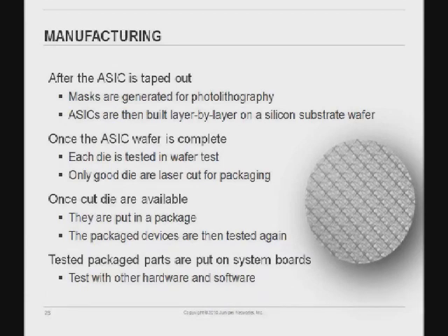And then that takes a couple of months, I believe. Once the ASIC wafers are complete, on the right side there's a wafer with a lot of chips on it, and each die is tested on the wafer itself to make sure it works. Then, when they work, we only cut out the working parts and put them in a package.